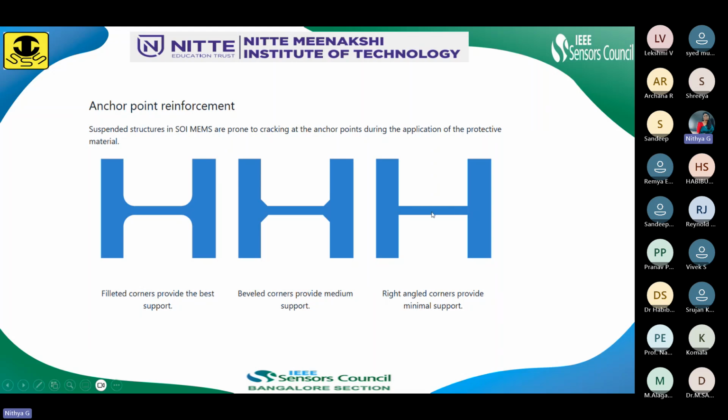One more point to remember is whenever we use a beam, let us consider a simple beam here. If the width of the beam is greater than 6 micrometer, then we don't have any worries in our design. But if the width of the beam is less than 6 micrometer, and the beam is anchored at one end, then the maximum length of this beam should not exceed 100 micrometer.